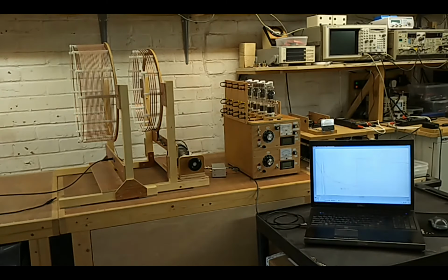So understanding the Z11, or the input impedance of this circuit, is very important, and this also tells you a lot about how it looks through the entire system. It's surprising how much detailed information you can get, at least from the transverse side of this experiment, by looking at the input impedance with a vector network analyzer.